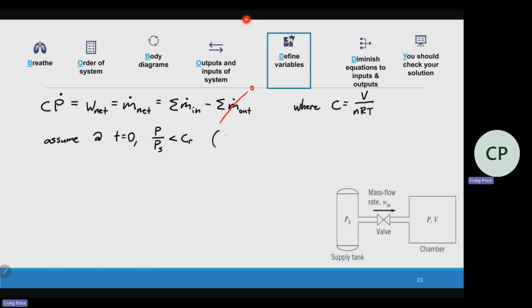And so this would give us a choked flow. Basically, it's capped by the area pressure. So we've got Mach 1 conditions. It's going to really flow in very quickly, and it's limited by some of those dimensions. And then later, once this kind of evens out and this becomes greater than the critical pressure ratio, that's where we'd be unchoked.